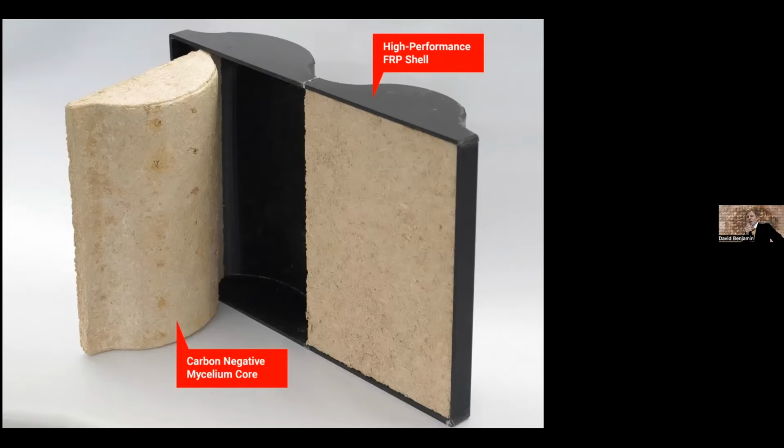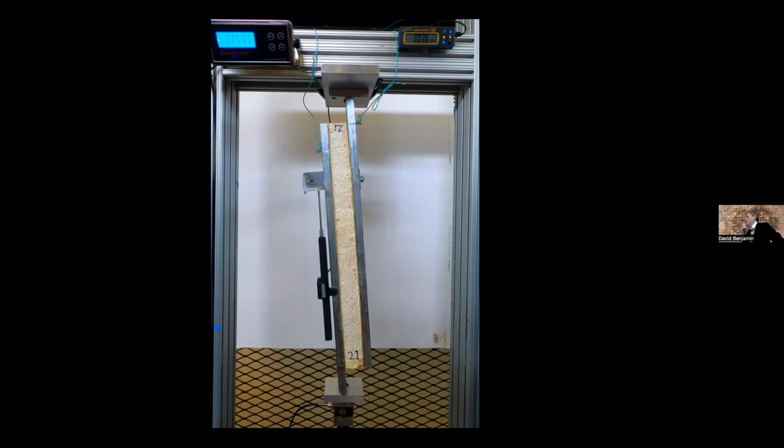And here's a different view of what we could think of as the traditional FRP system. If you've ever seen the facade of the SF MoMA, this is the kind of addition. This is the kind of system used for that. It's an FRP sandwich panel, and we're replacing what's typically the middle of the sandwich, an EPS foam, with the mycelium material. So this required us to make a different version of mycelium material than we had used before.